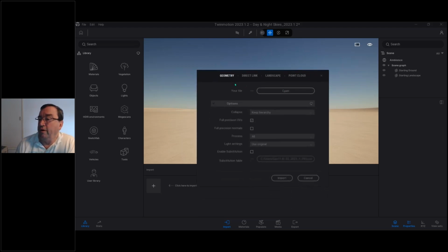If I leave my hierarchy here, because what I want to do within this is keep the hierarchy. In other words, all those components I've got in Revit, so the walls, doors, windows, everything like that, are kept in here. I don't want to collapse it all by material because perhaps I might want to change some of the materials on certain walls without all the material changing.